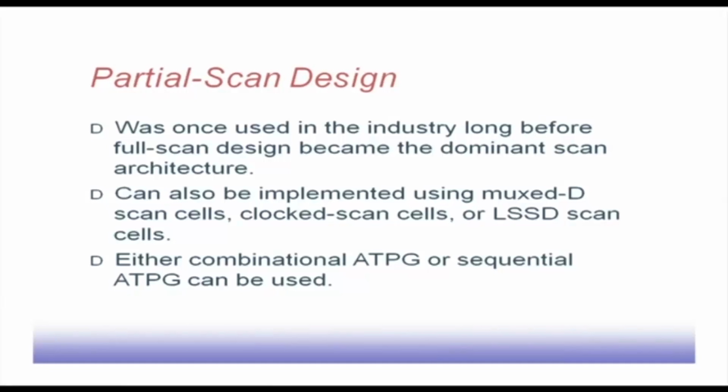The patterns dedicated for testing combinational faults may also become sufficient for testing these types of faults, so many of them will get detected. Or we can use a sequential ATPG, which is more complex, for generating this type of test patterns.